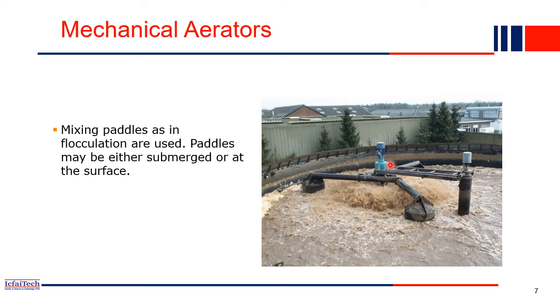The first step in the water treatment process is the aeration, right? After water comes from the raw source, it will first come into the aeration tank. It will stay for half an hour or 1 hour depending on the pollution level, and then water will pass to the next chamber. In this mechanical aerator, at the center, this type of machine will be connected, and it will simply rotate throughout the tank. Each machine will also have three legs, and this entire part will be rotating across the entire tank.